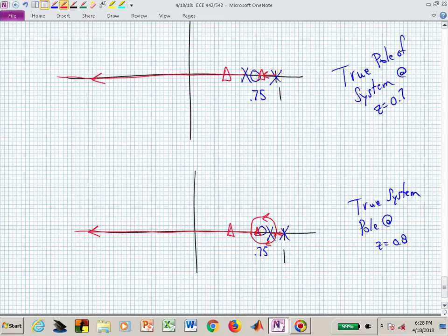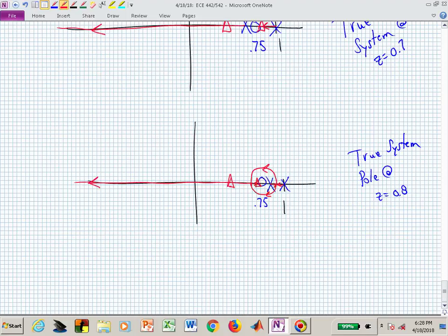That's how you could now start to analyze or examine the behavior due to uncertainties in your system. And this root locus analysis is sort of saying, you know, it's a pretty robust way of designing controllers. Our closed loop system response didn't change that much, even when our system changed a little bit. And we didn't have to necessarily exactly cancel the pole with the zero. And we still had pretty good behavior. That's the takeaway from that.